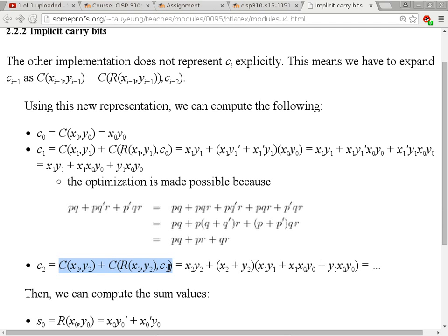Now this one can probably be simplified a little bit more, but it will still be a pretty long and complicated expression. But the nice thing of doing it this way is the carry bit out of the second least significant column can now be calculated by just looking at the least significant 3 input bits. And I don't have the propagation delay problem anymore.